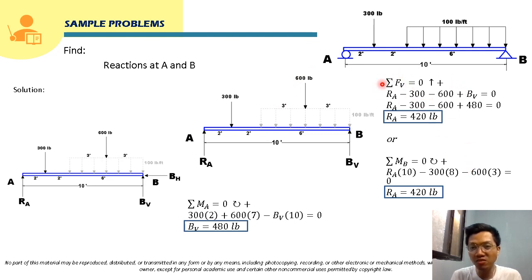So either of these two, you can use summation of forces or summation of moment. This is mentioned in our discussion that when you are solving equilibrium of a parallel force system, you can use a combination of one moment equation and one summation of forces, or you can use two moment equations at different points.